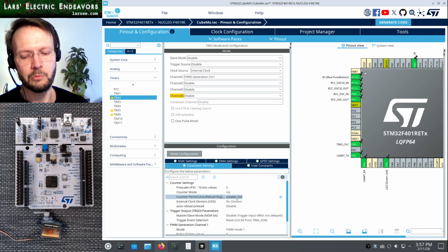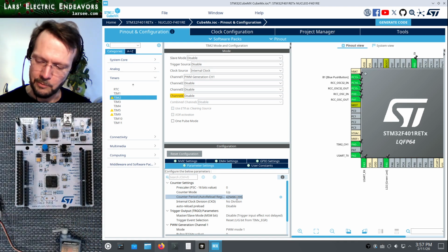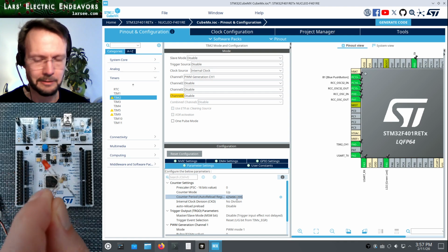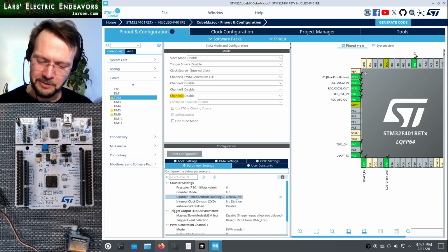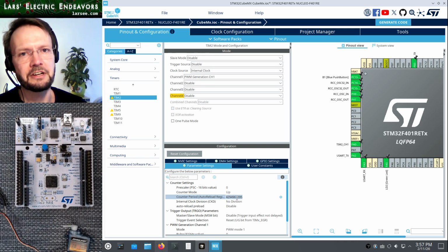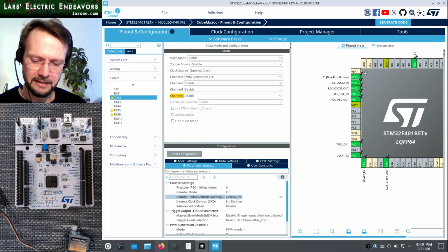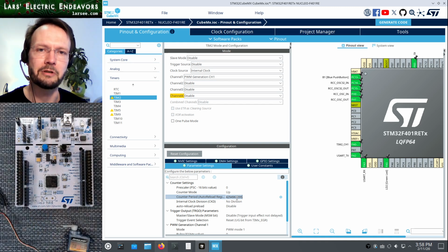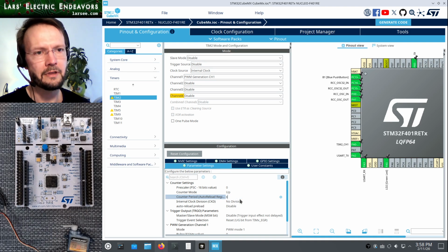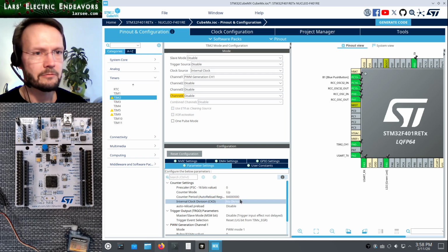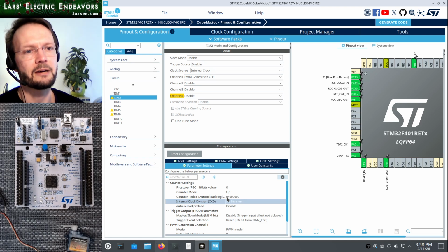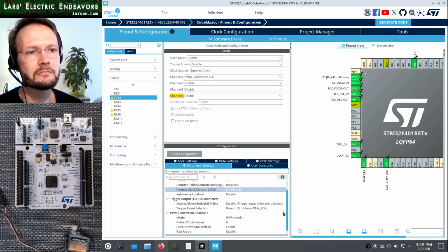And what we will do now, we will not start with the servo. We will start with an LED. Look at my little construction here. Because we want to make a sanity check that we actually are generating the pulses like we want them to. So what we will do now, we will make the LED blink once per second based on this PWM output. And if I type 84 million here, that means with an 84 megahertz clock cycle going into the timer, it will reach the period once per second and restart. So like this, we will have a timer with a 1 second period.